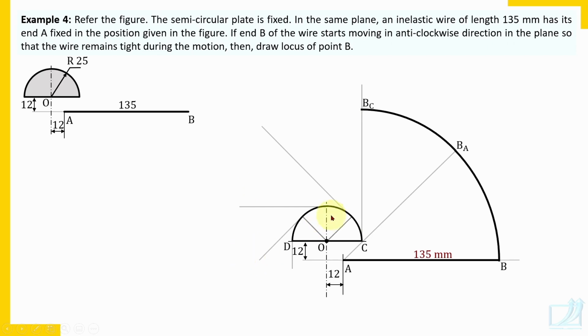So we should use the procedure which we have used earlier. How much length of the wire will get winded over semicircle? Equal to semicircumference. That is why, because it is a semicircle, and how much length gets winded over semicircle? It's semicircumference. So it's not pi d, but pi d by 2. Pi d by 2, you should divide it in 4 parts.